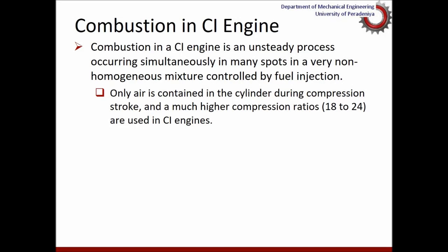Therefore, there is no homogeneous mixture preparation as in the case of petrol. So diesel combustion is not a pre-mixed combustion. The flame diffuses into the unburned gases rather than propagating from one point all across, as in the case of petrol.